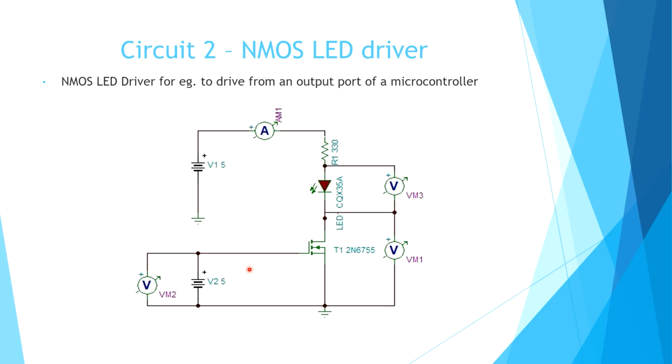Okay, so I have put in an ammeter to measure the current. This is the 5 volt VDD. I designed this resistor for 10 milliampere, so 330. VDD 5 equal to ID into 330 plus VD, we have taken 2 volt, plus 0. So that will become 10 milliampere current, or approximately 10 milliampere, or 9.9 milliampere.